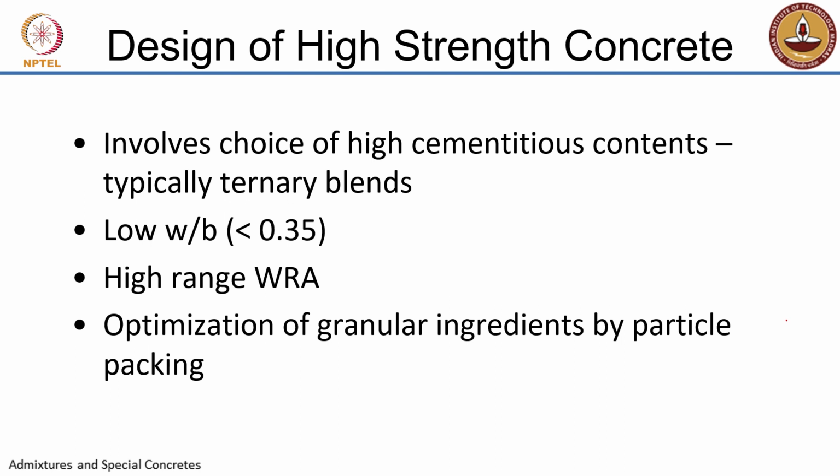One of the examples we saw previously was in one of the approaches when we discussed biomass ashes. They were looking at applying compaction during setting. When you apply compaction during setting, you are obviously overcoming this issue of void creation by suppressing the voids from forming. And that is one way of increasing the strength of your material.